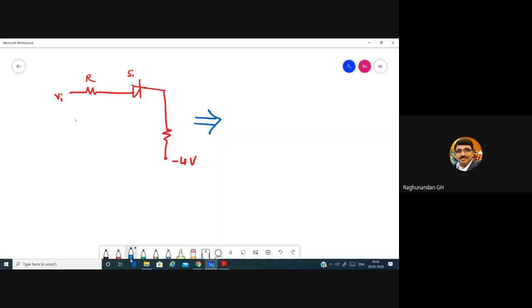So this is plus, no? So consider a battery, positive, negative, and after that a resistor, and as they are telling approximate model, see, if they are not telling approximate model, there is no need of considering the silicon diode as a battery. You can directly consider the voltage drop of that as some V. Now they are telling approximate model, so consider it as a battery.